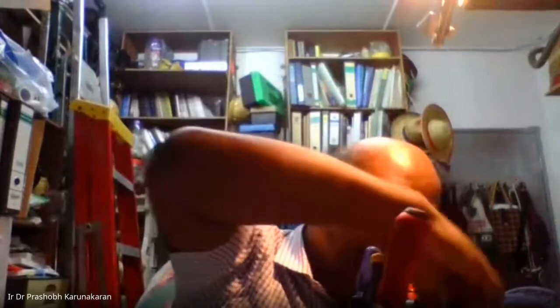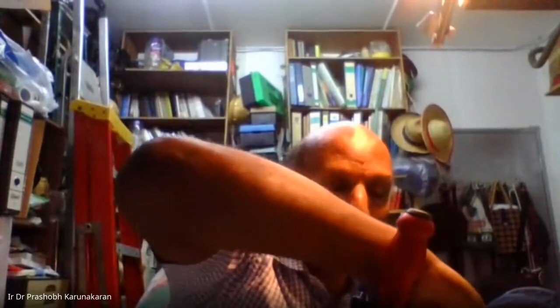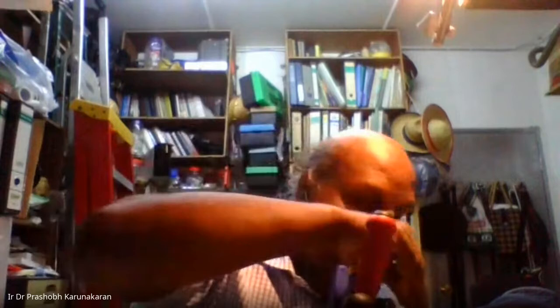I bought this, which I find in my electrical job I use a lot, now to cut big wires. This one, any big wire also can cut. Okay, knife, very important. You have a good pen knife. Why? When you insulate a joint, you roll on the tape. You don't go and pull. When you pull, you damage the insulation. So you just cut.